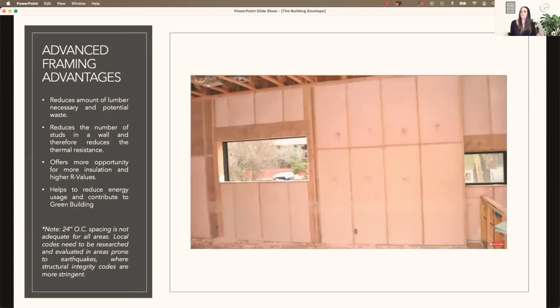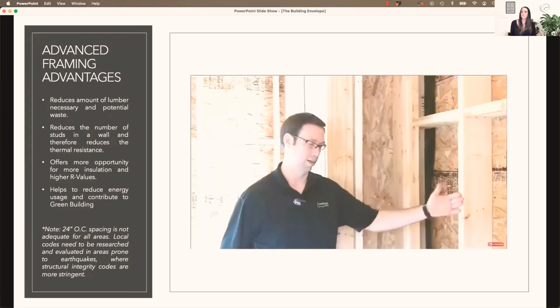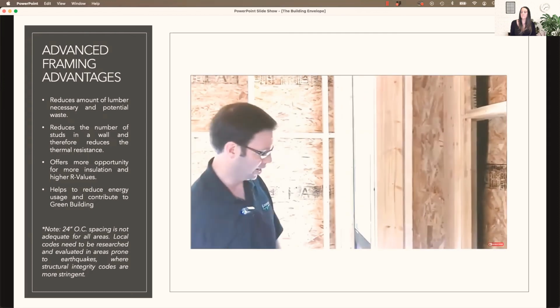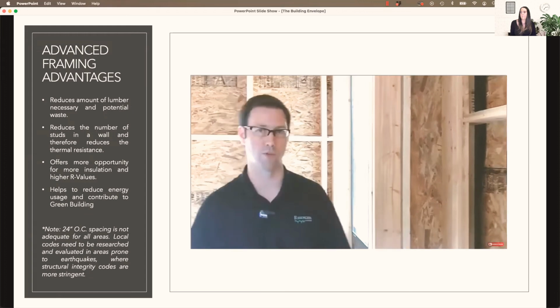And then we're going to do a total fill installation on this cavity. I'm actually going to use Owens Corning Energy Complete. So this entire cavity is going to get R19 packed full of a blown-in blanket. Really good insulation system. On the outside of the house, we're doing 3/4 inch rigid foam.